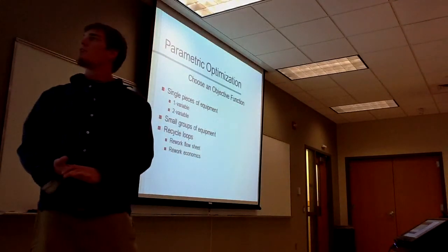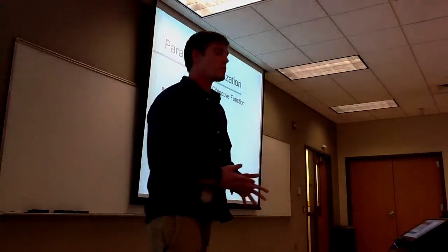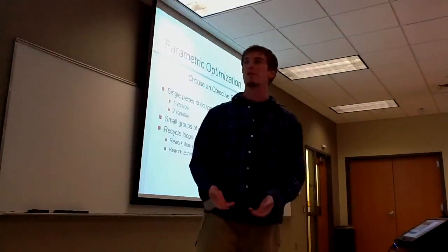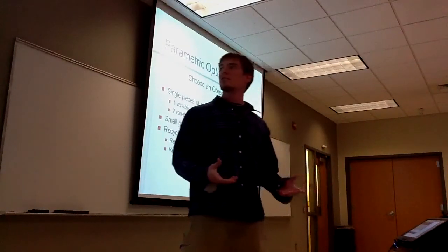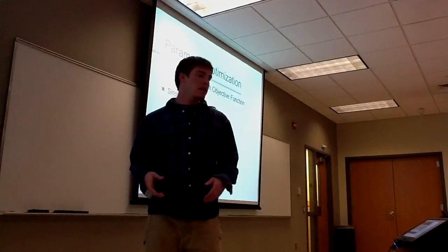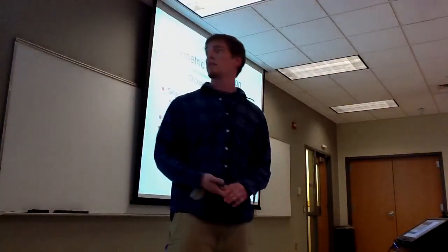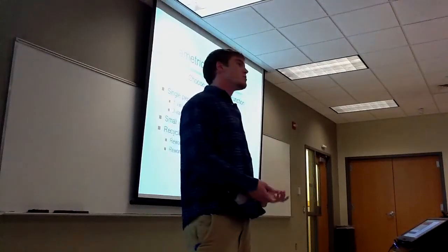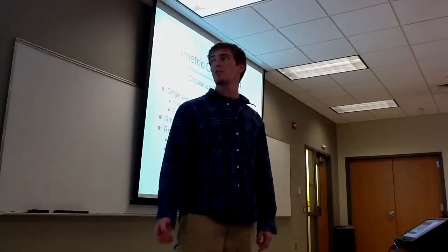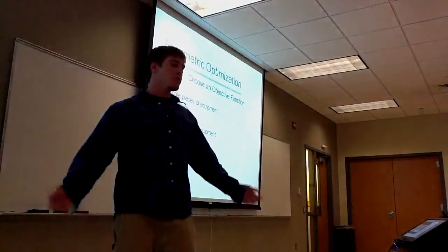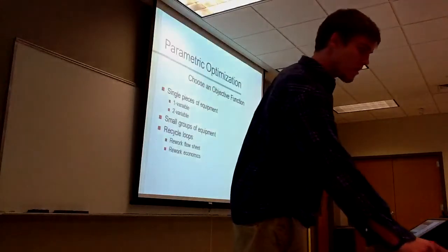To start off, you would want to analyze single pieces of equipment, starting with one variable, then moving on to two variables, and then multivariable. Then you'd move on from there to groups of equipment and do the same process. And then you'd want to analyze recycle loops. When you optimize recycle loops, it can affect all the pieces of equipment within it, and you might need to rework the flow sheet and rework economics again.